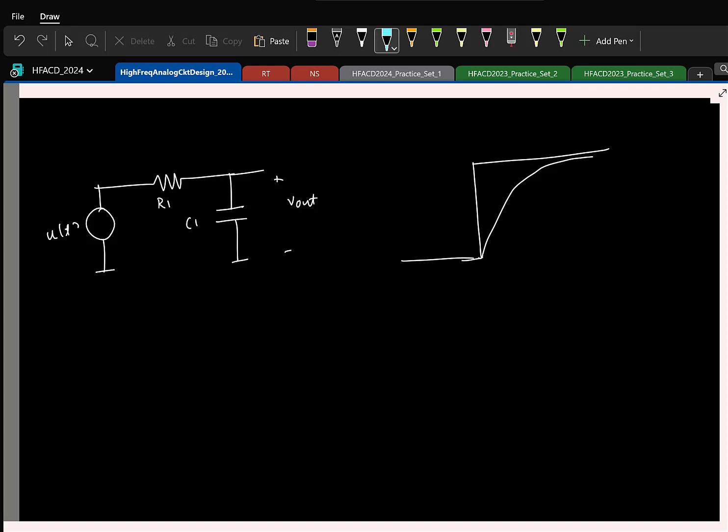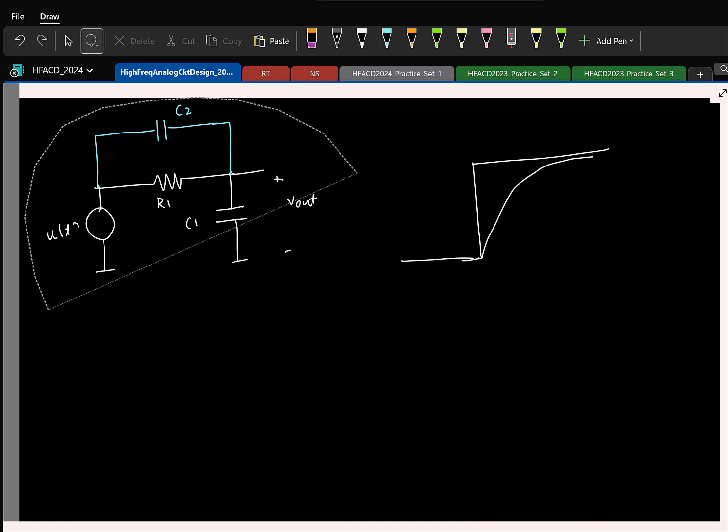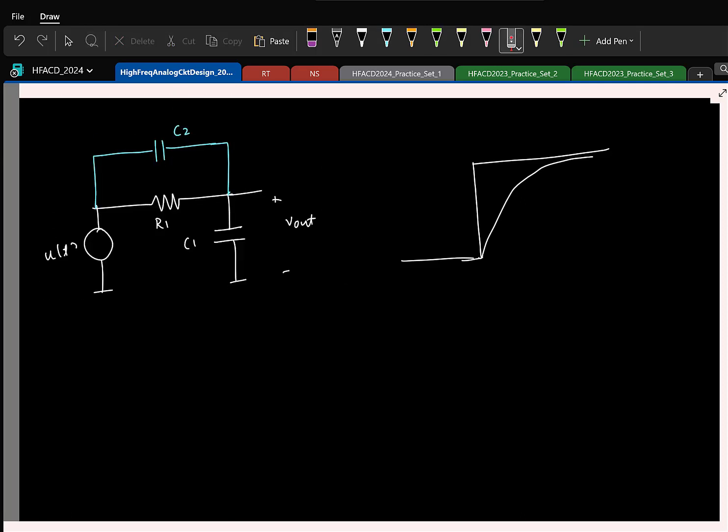Now let us say I go and put a capacitor across this guy. Say this is C2. Now how many poles do we have? One pole, because to find the poles you short the input and you see these two capacitors are in parallel, with just one independent state variable you can initialize. Do we have a zero in the circuit? Yes, you can basically short this capacitor and still the output is non-zero. Even qualitatively speaking, I have currents from two different branches getting added up. They will have different phase shifts. So at some complex frequency we'll have the zero. Okay, so it's a first order system again, but with a zero.